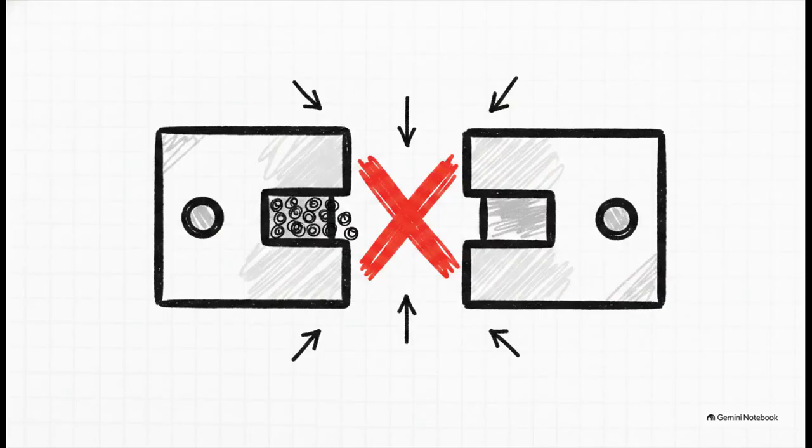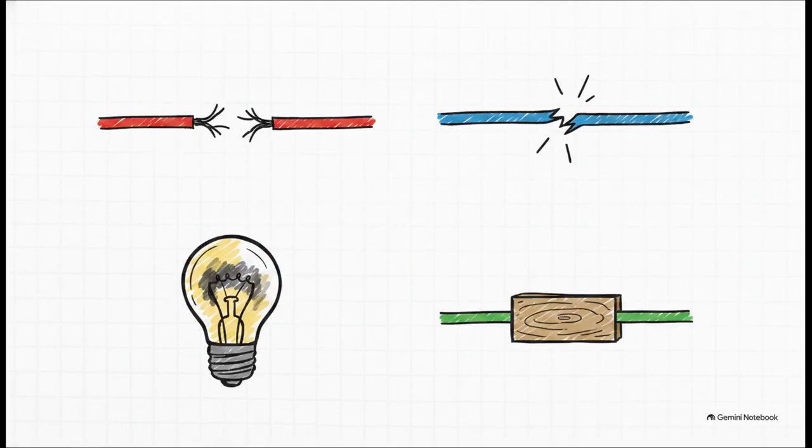Because that path is fundamentally broken, the entire circuit is operating in an off condition, meaning it just does not conduct electricity. As a direct result, zero potential difference occurs between the 2 terminals of that open switch. It's essentially a dead end for the energy. Without a connected path, there's absolutely no electrical pressure pushing those electrons forward. And it's really important to realize that a manually open switch isn't the only thing that causes this state. If components naturally disconnect or break down over time, boom, the circuit immediately functions as an open circuit. This usually shows up as a fault condition in your everyday devices.